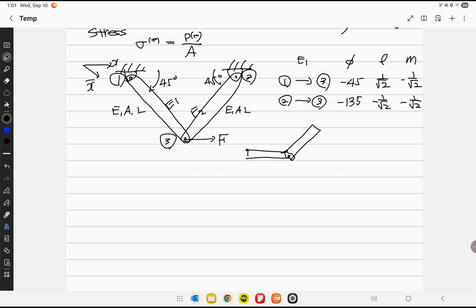The shape of the bar, the shape of the beam, the shape of the shaft, all the mechanical components that we talk about are indeed identical. So why do we sometimes call it a bar, beam, or shaft? Their mechanical role changes. If I take this one and try to twist it, I call it a shaft. If I try to bend it, I call it a beam. If I try to push it back and forth, I call it a truss. So we have a very interesting geometry that is not just a straight line. If they are not pin joined but welded together, then you need to use the beam, which is the topic of the next chapter. So let's go slowly. We don't jump to the beam at this point. Any other questions?